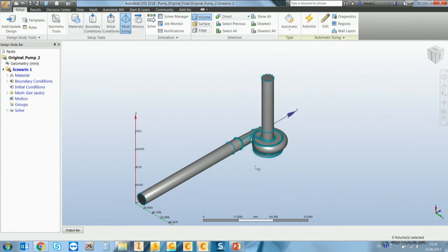The most important regions that you have to take care of when simulating rotating region analysis are to refine the leading and trailing edges of the blades of the impeller, because they are the regions where high gradients of velocity and pressure happen.